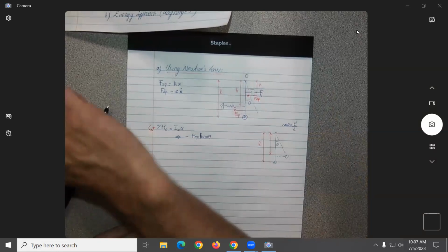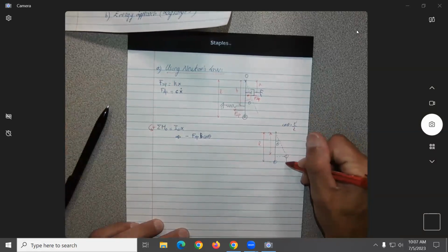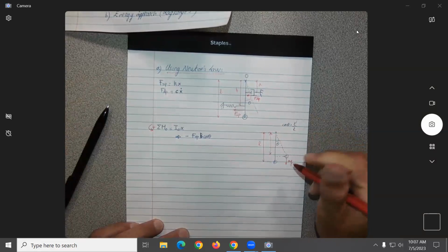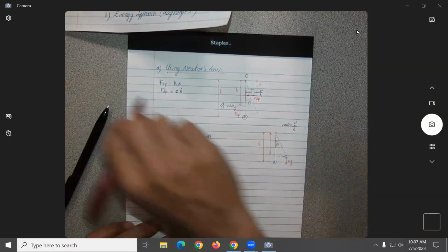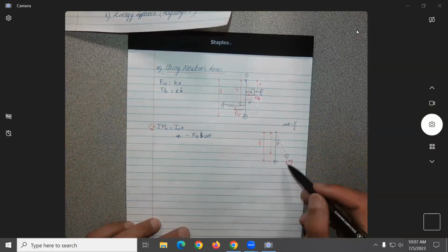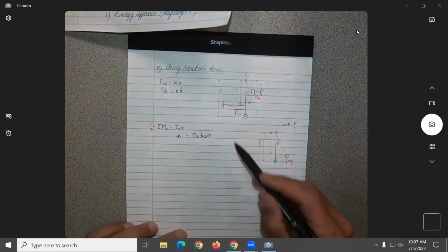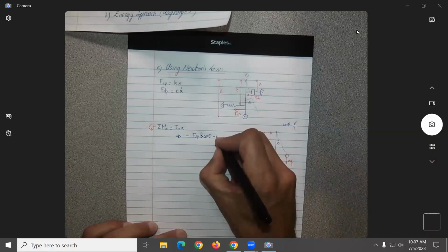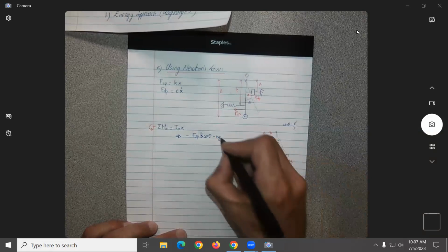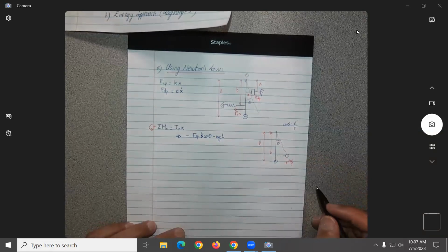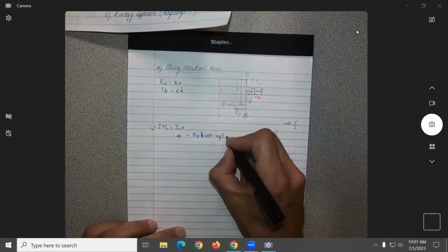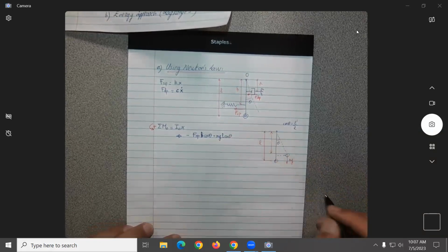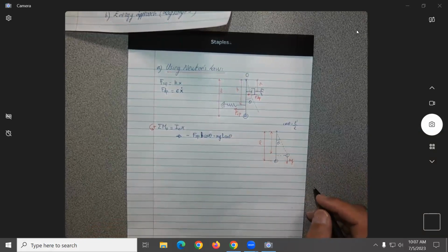Now, since I have the speed over here, we need to be careful. I didn't put it here, but we're also going to have mg when it's moving. So now mg will be creating what, a counterclockwise positive moment or a negative moment? It will be going clockwise, no? So it will be minus mg, and this time times what? L times sine theta. So we took care of that.